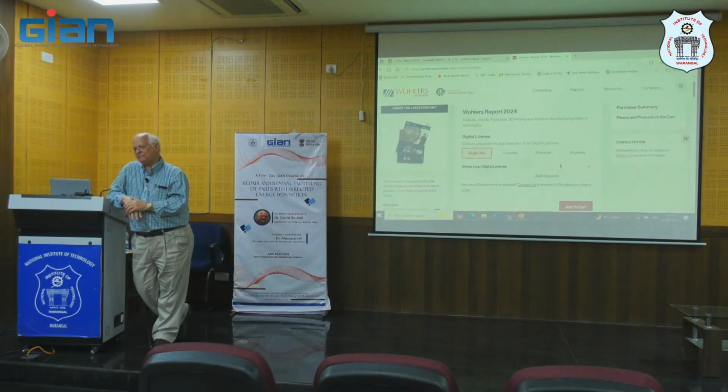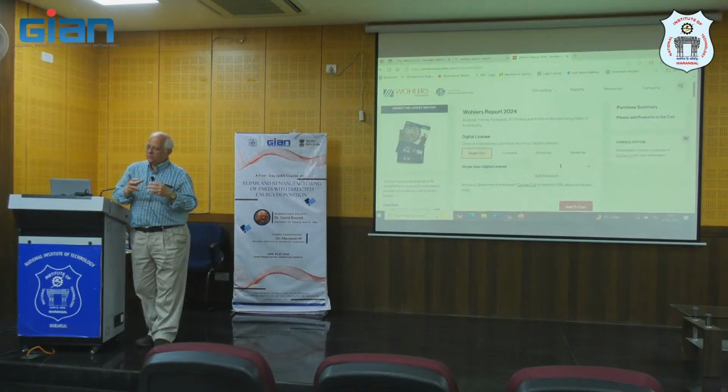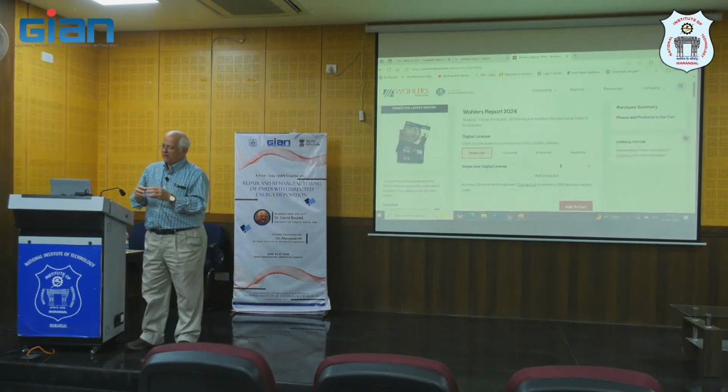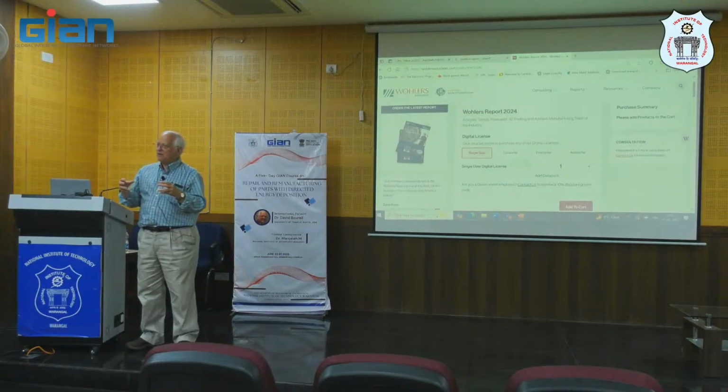There's one other area: metal implants where they use laser sintering, but it's not because it's a customized geometry for a specific patient. They build these parts by additive manufacturing, but in standard sizes. It's like shoe sizes, where the surgeon would just grab the one that they think will fit the best, closest good enough.